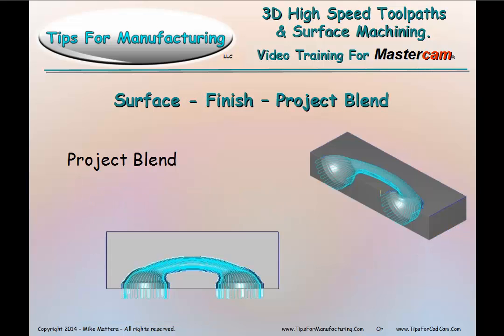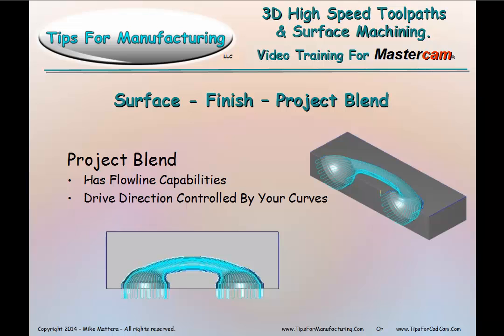But another one is the surface finish blend. This is actually in a different category of toolpaths. So this has some flow line capabilities. You drive the direction controlled by your curves.